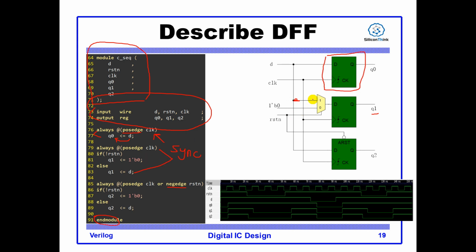So this is equal to a mux before the D pin of the D flip-flop. If this signal is 0, it will pass through the mux and be captured to Q1 at the rising edge of clock. Or if this signal is 1, the value of this path will be muxed to here and registered at the Q1 output. So this is exactly the function of a synchronous reset DFF, or you can say a DFF with synchronous reset.